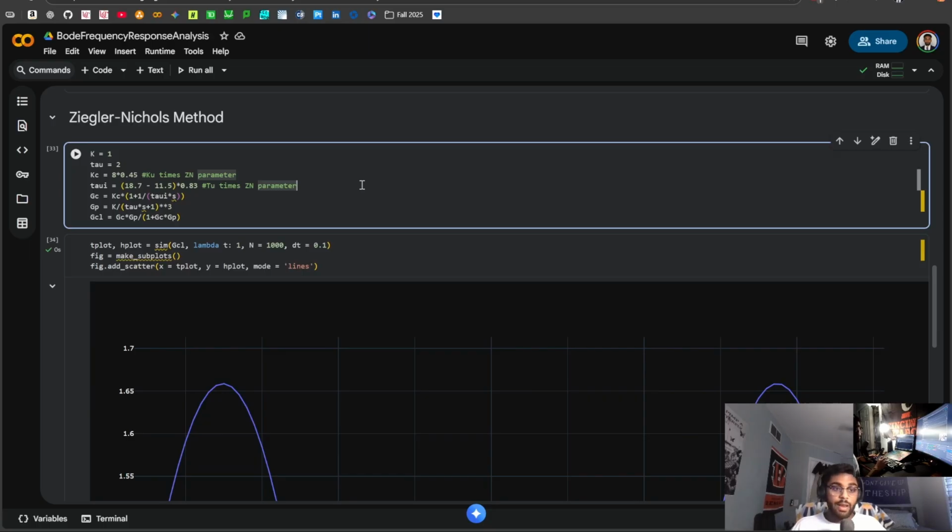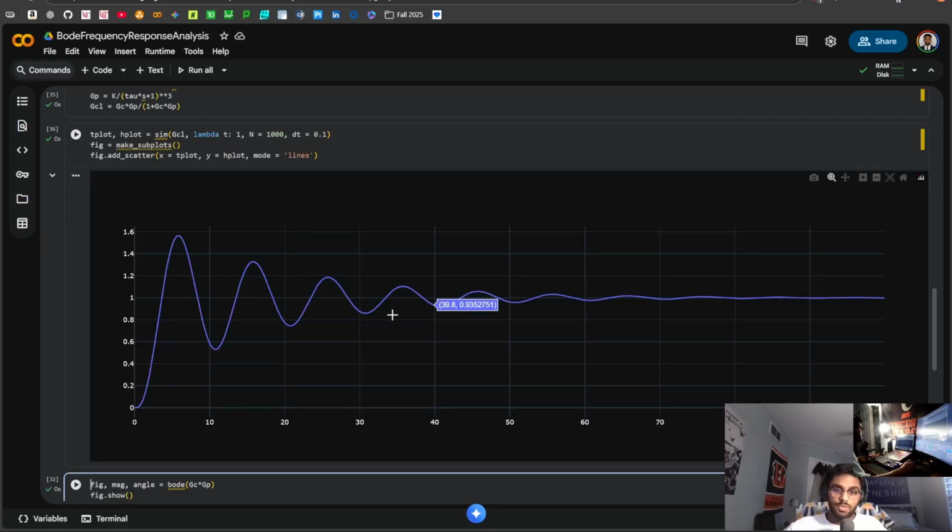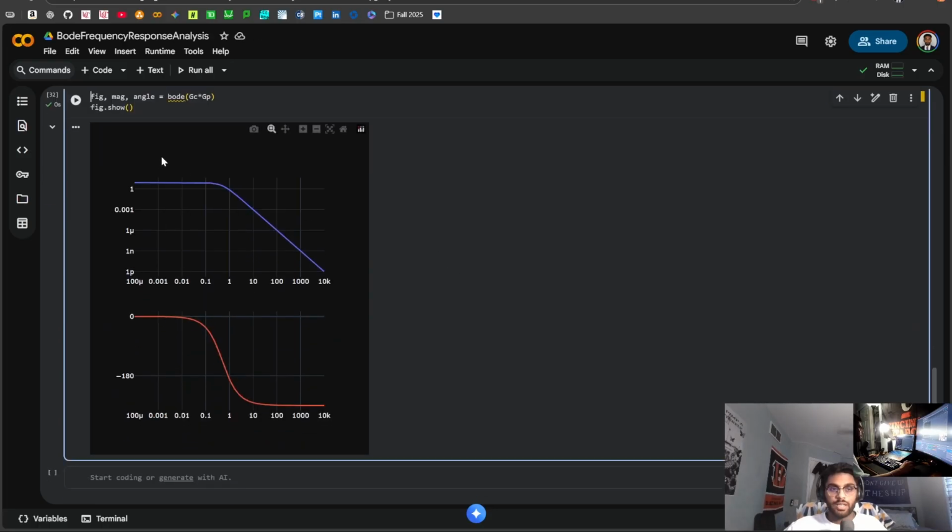Okay. Now if we run this with the new values, we see that very similarly, we run this to a steady state, and this is representative of the previous setup before we did any messing around with using the Ziegler-Nichols method. We find that our crossover frequency is at about 0.87, and if we try and find that on our graph, 0.87 gives us an amplitude ratio of 0.99, which is very, very close to 1. So we were correct in that assumption that this is that critical K value, that ultimate K value.